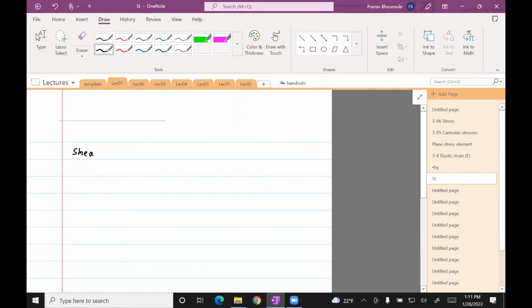If you start off with a rectangle and you load it with a shear stress, now what will happen is this is sliding, so it's going to cause this rectangular piece to be shaped like a parallelogram. And of course, this part is fixed, or grounded, so it cannot change its position, but it will simply change its shape.